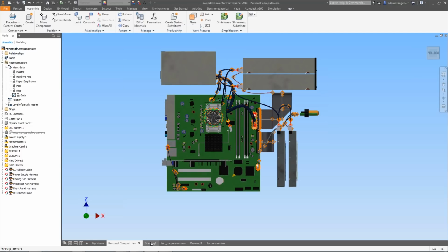Automatically, when you create a new assembly file, and I think even part files now in Inventor, it creates two view representations. There's the master view, which is everything and is locked, and then your default view. It creates both as standard on your part files or assembly files, and it automatically activates the default view. So if you're wondering why there's one called default in addition to master, it's automatically generated when you start an Inventor file. Hopefully that answered that question.